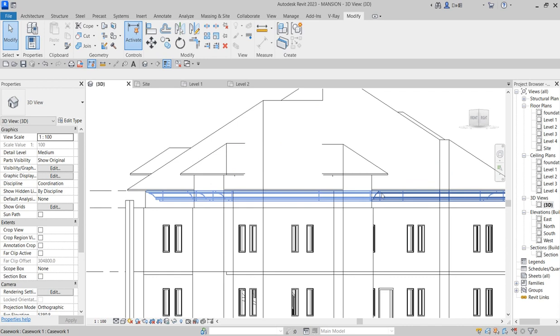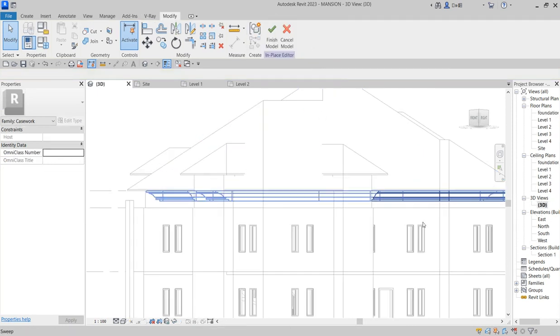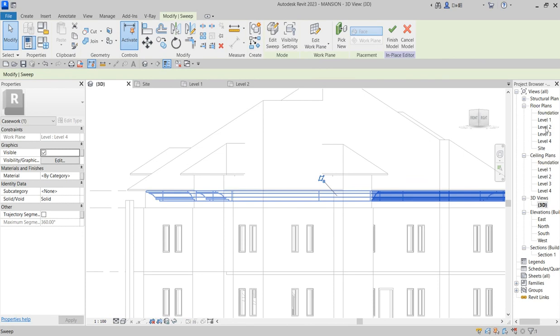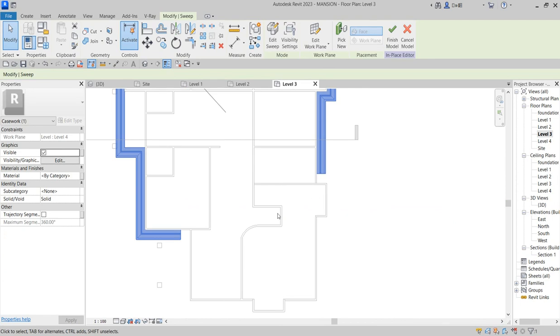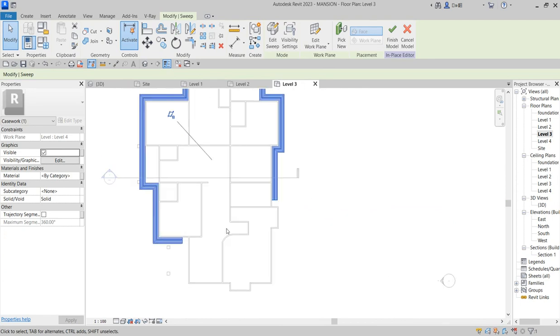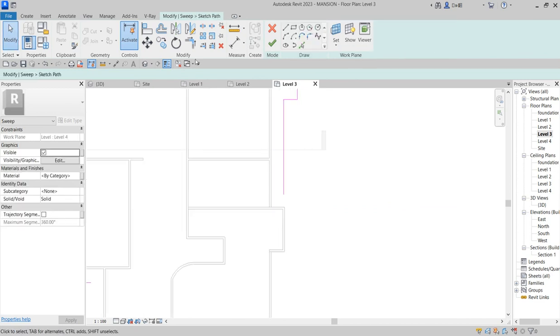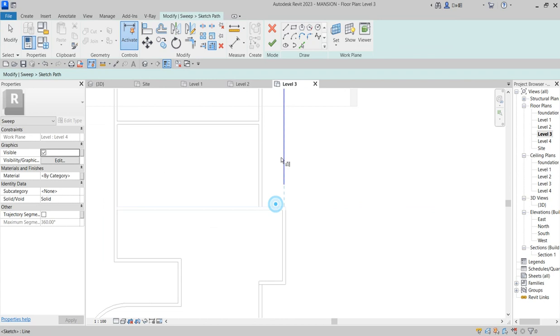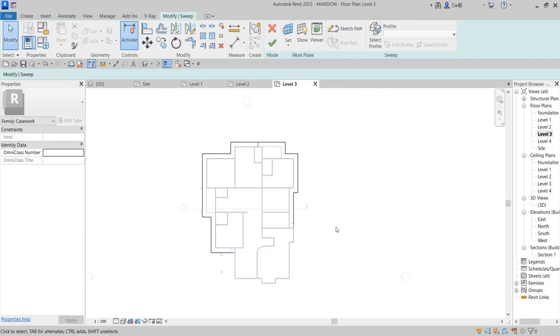So now what we do is that this particular one, we continue doing it the way we want to do it. So click on edit, then you go to select this and go to your foundation, level 3, where there is a certain act of roofing. So from here you edit this, then bring it close to the wall. So they will have close contact with the wall.